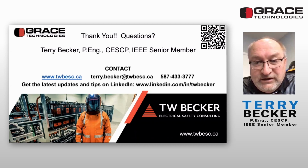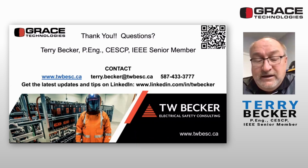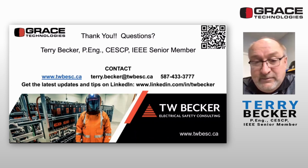So I'm trying to rejig the context of the question that was just asked around that direction, right? It's not just that on that equipment there's exposure. No, it's the work task, and then we perform it on that equipment at some maximum nominal voltage that's in the box for electrical hazard identification, and then do our arc flash and shock risk assessments to get the boundaries and the shock and arc flash PPE, tools and equipment.